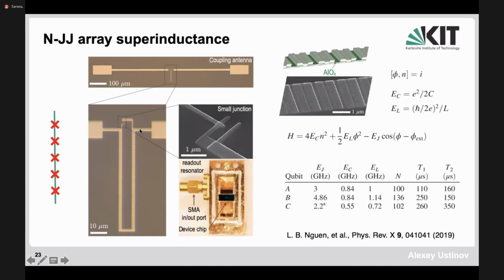And then on the right here, you see the additional resonator, which is a coupling antenna. This antenna actually is needed to increase the dipole moment of the fluxonium, which is coupled to the field in the three-dimensional cavity. The frequency of this antenna is, of course, different from the frequency of the transitions in the fluxonium, but nevertheless, it can also be observed as a coupling mode to the three-dimensional cavity. But its role is basically to couple the electric fields of the cavity into the fluxonium through these coupling fingers.